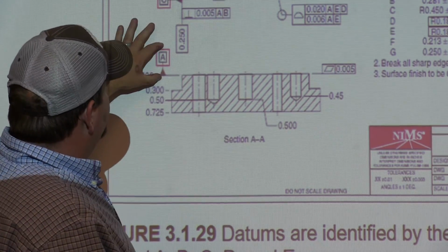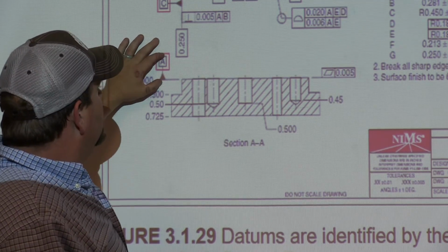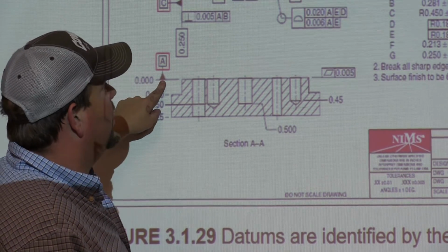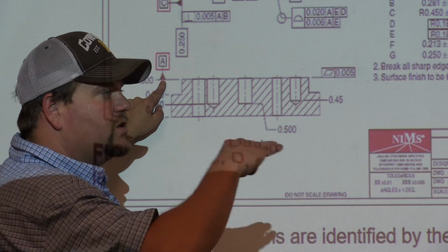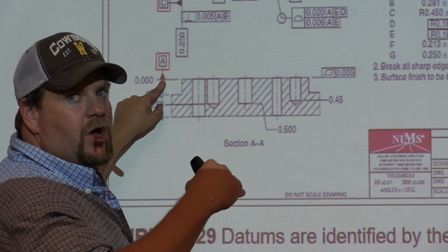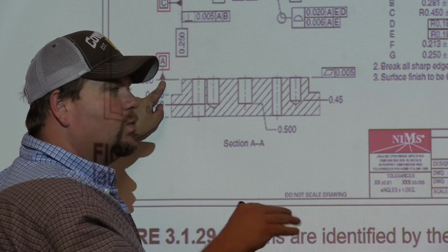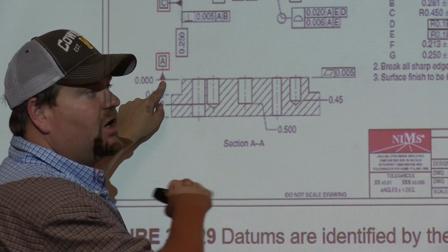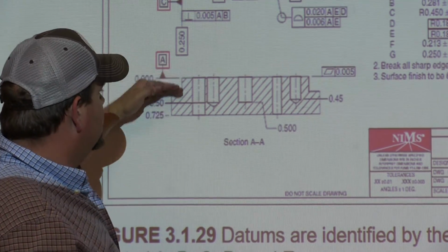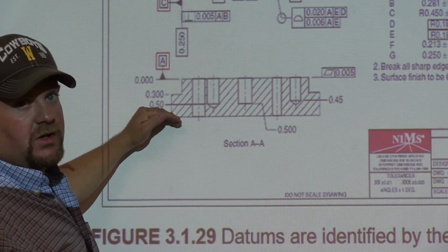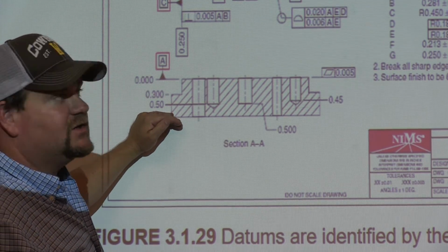So what it's saying is your datum line here is the top surface. This is the finished surface. This is datum A. Alright? This is very common in a machining operation. We'll come in and face off the top, the stock, rough scale, and so forth. We machine it down, and then we start measuring from there. Okay? This is going to be our through thickness piece, so this could be referred to as our Z dimension, or our Z axis.